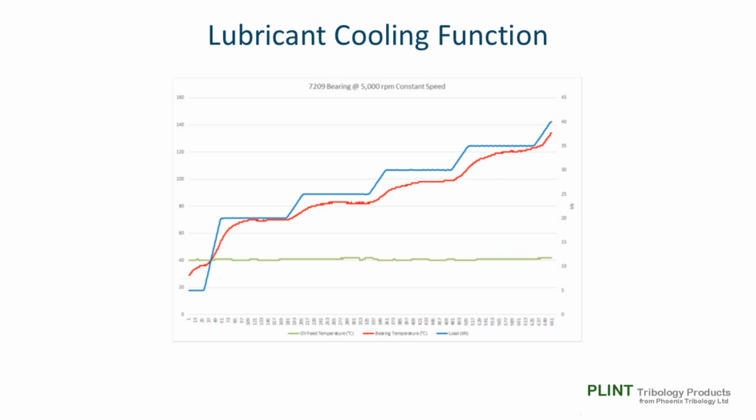A corollary to this observation is that with a controlled lubricant supply, it may be possible to achieve a lower stable bearing test temperature with a higher lubricant inlet temperature, hence a lower lubricant inlet viscosity, and at a lower flow rate, hence lower churning losses, than with a lower inlet temperature and/or a higher flow rate.